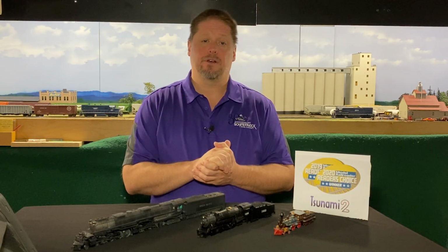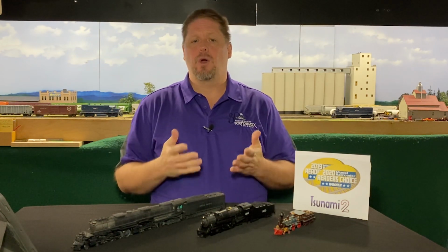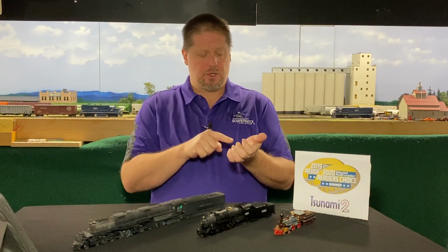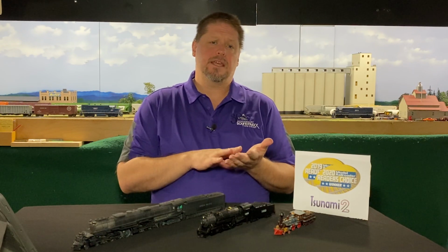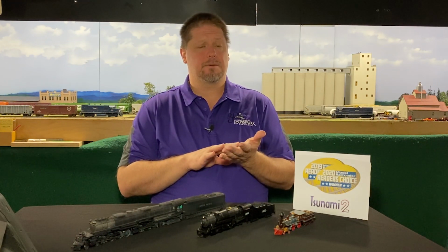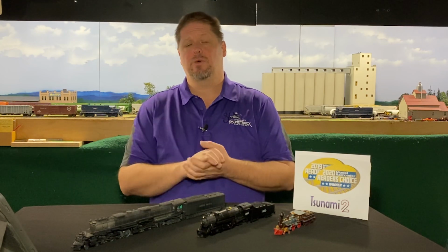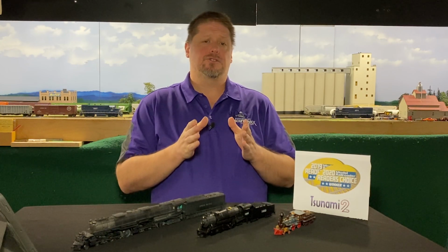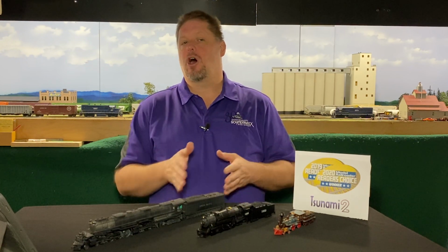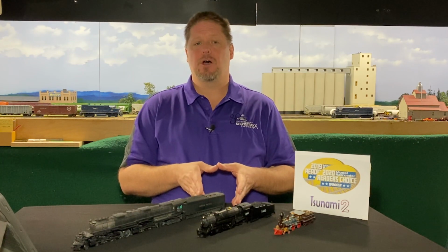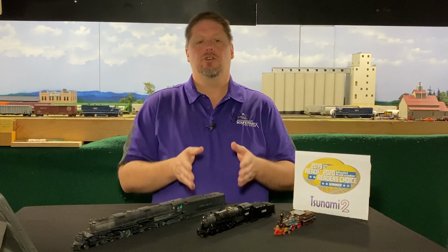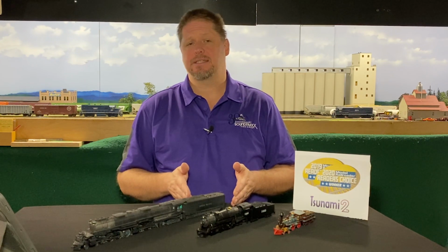Now, let's talk quickly about how we'll do it, and then we'll show you a quick example of how it works. So F11 is the brake application. So when you press the F11, you're actually applying the brakes. Now, the independent and the automatic both have their own independent braking rate that you can determine with a CV. Now, to determine which brake plays, CV112 is either on or off. Default is off. Your locomotive is in independent brake mode. So when you hit the F11, you're hearing the independent brake sound.